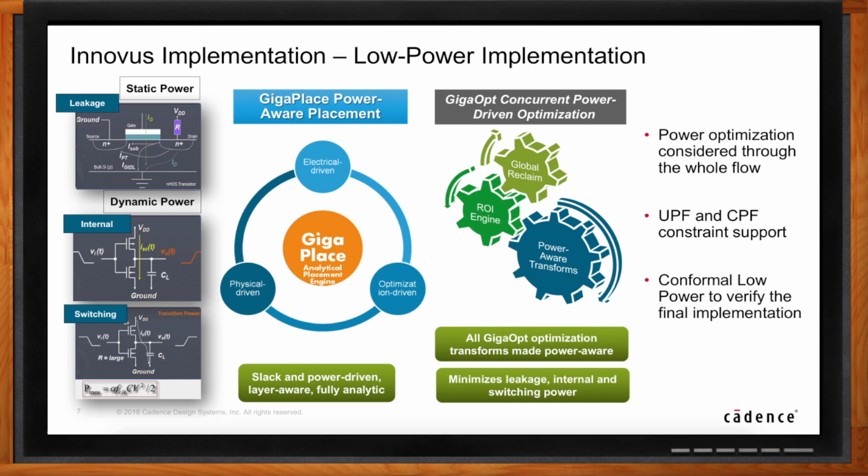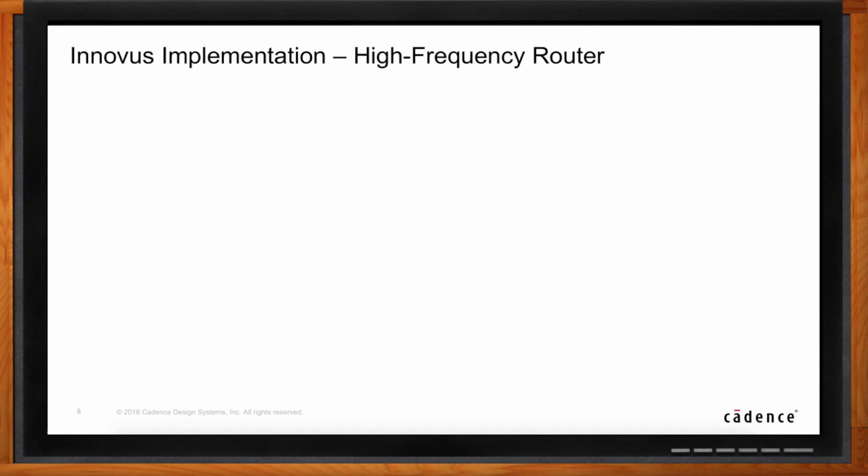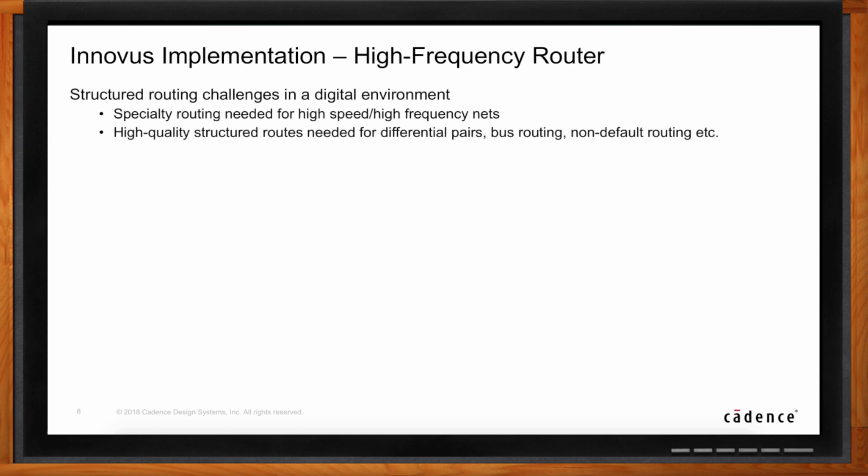Very cool. Okay, so what about my high-speed design? I have to do all kinds of special stuff for the higher frequency parts of my project. Yeah, absolutely. This is an important capability. And this is a little bit unique to the mixed signal design. The mixed signal designers have many more specialized routing constraints than a regular digital designer would have to cope with.